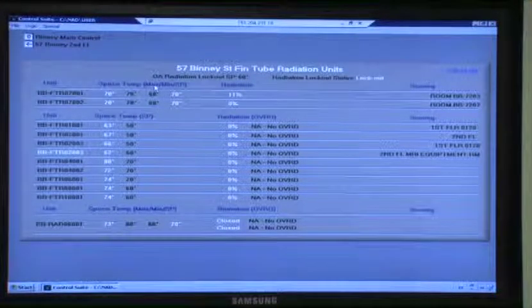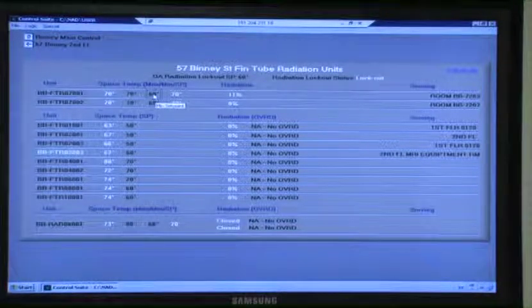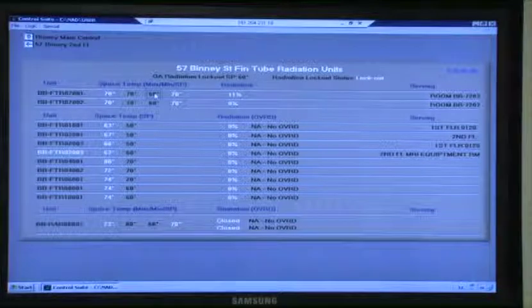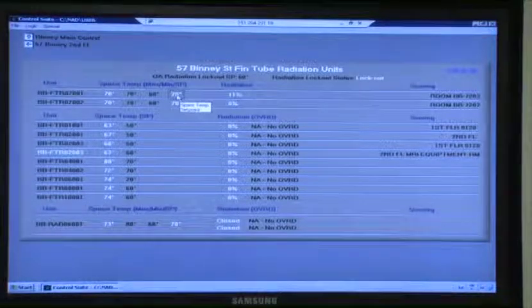Like Steve said, you have the space temperature and you have a min-max. They can adjust the range of their set point, what they want inside that space, between 78 and 68. They can adjust it by the occupant thermostat of the room. There's a thermostat setting, and these are the limits they can set. There's only a couple in the building, so it's just a way to identify it.